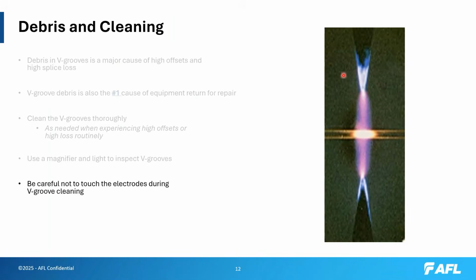What it would do is create a path of least resistance. It's a bare metal location, and that arc would jump not from tip to tip, but it could possibly banana arc and move over to the far left or far right and not arc properly as a result of that silica oxide being knocked off by the cleaning agents or the cleaning swabs.